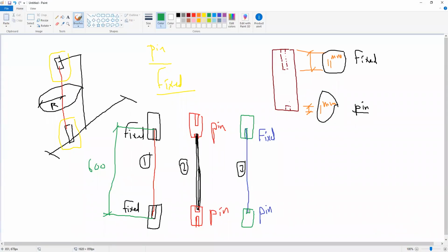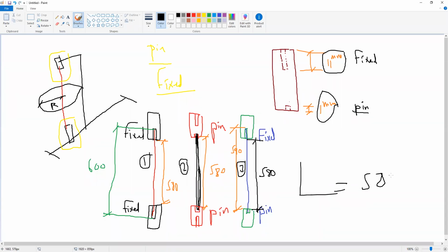Yeah, here for the first case, can you see now? Yep. So from here to here is 600, but because you lose 10 millimeters at the top and 10 millimeters at the bottom, this gives you 580, right? Here as well, it is given to you directly as 580. Okay. Here the length is 590, but because you embed 10 millimeters in the top of the column, the clear length will be 580. So the length for all of them in the testing, just to compare, is 580 millimeters.